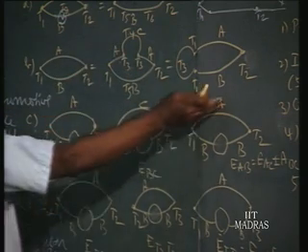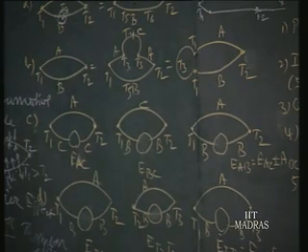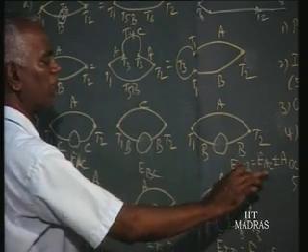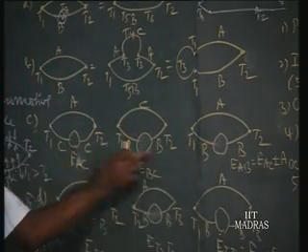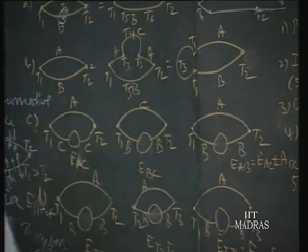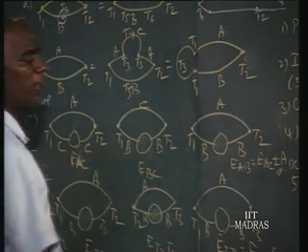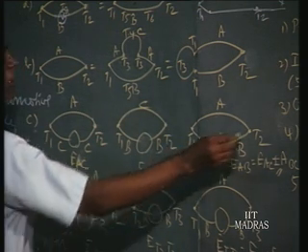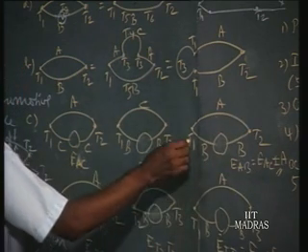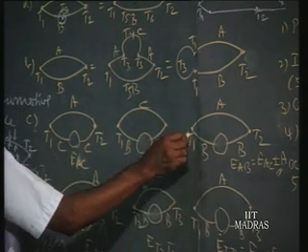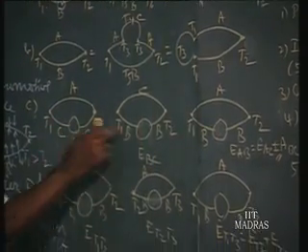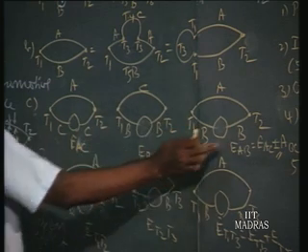Platinum is the common material. Then if you have a thermocouple pair between A and B, the EMF developed for that same T1 and T2 is obtained. EAB is given either by addition of these two voltages or the difference between these two voltages, as written here. And whether plus or minus, how to fix that? At least at one temperature, with T2 as 0 degree centigrade, and any known temperature T1, find that voltage. For that temperature difference, you can check whether by adding you get this voltage or by the difference.